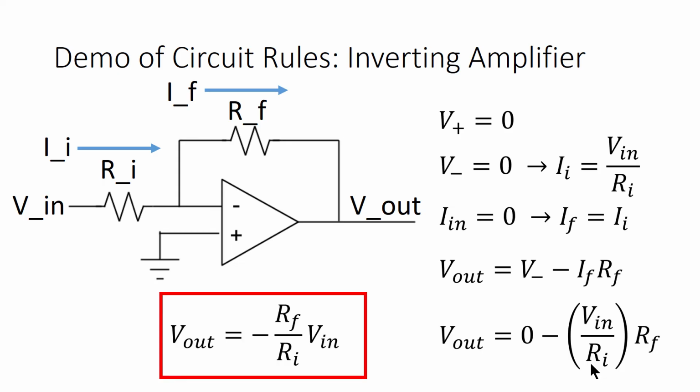Finally, this expression cleans up rather nicely to show that the amplifier gives us a negative gain, which is why it's called an inverting amplifier. Now just to describe this in exhaustive detail, the gain is equal to minus Rf over Ri, which is negative. So a positive voltage on V in will cause V out to try to produce a negative voltage. We'll have a whole video about op-amp power supplies later, but note that this op-amp would work really poorly if the negative power supply was at ground, because V out couldn't ever reach the value it was aiming for. It would just rail out at ground.